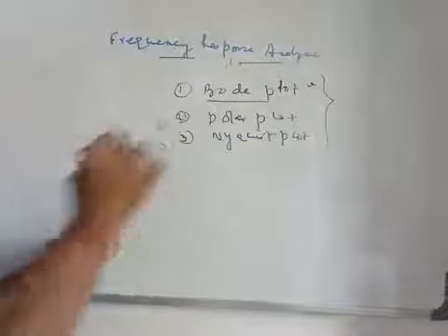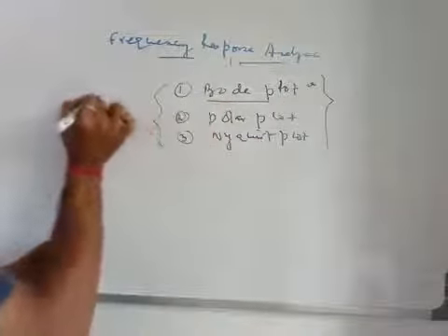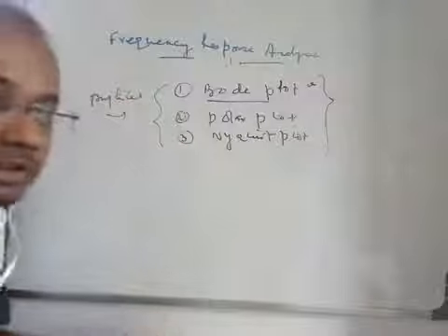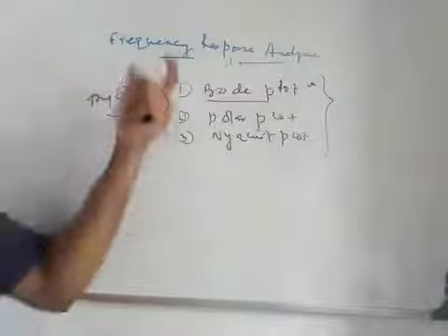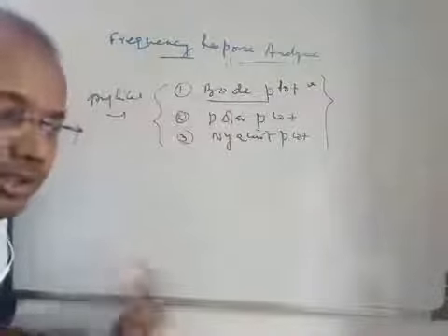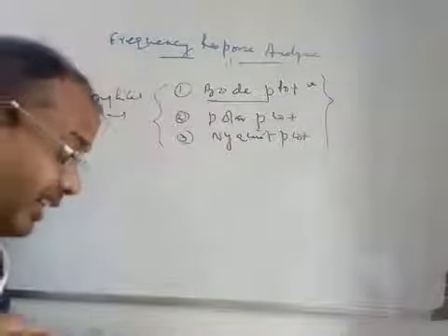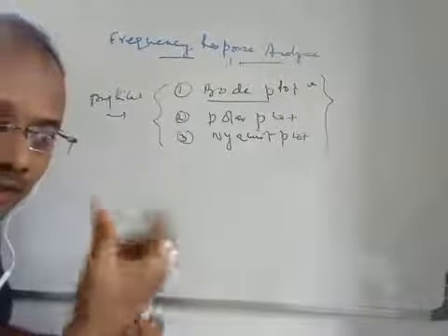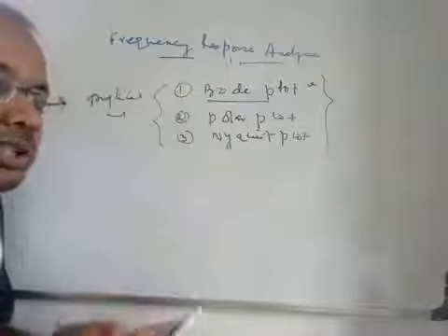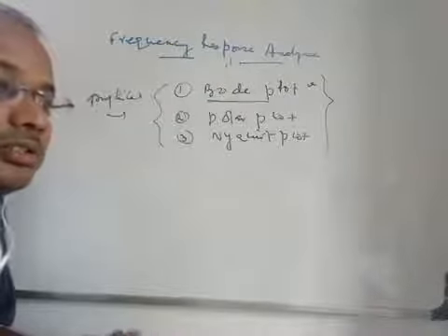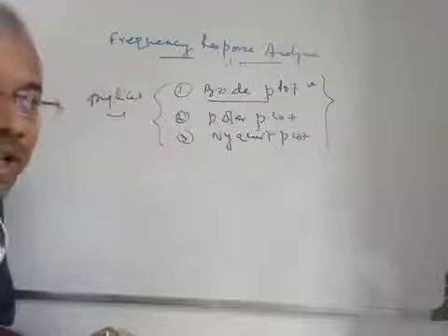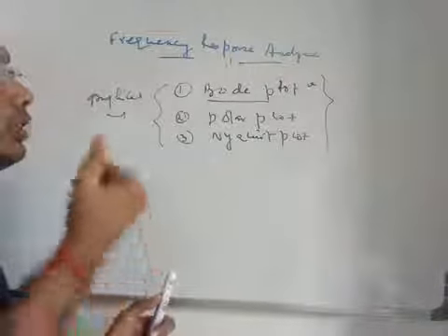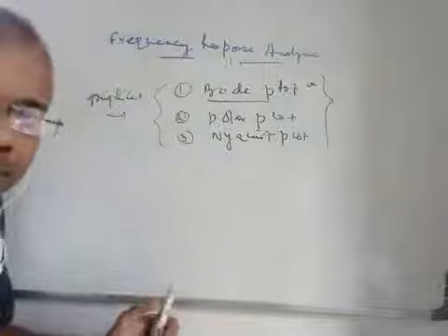These are all graphical approaches, because in the time domain analysis also there were defined methods, graphical and analytical, and here all three are graphical approaches and very interesting methods. The mathematics can be very easily expressed by graphs, and from the graphs you can easily observe whether the system is stable or not, in which frequency range the system can be made stable, and after which the system becomes unstable. These are all the aspects we are going to discuss in this chapter, that is, frequency domain analysis.